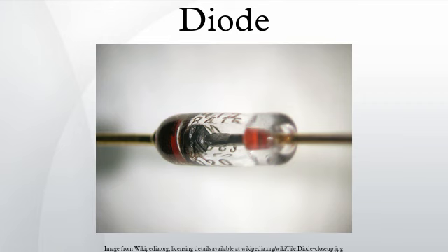These are Avalanche diodes designed specifically to protect other semiconductor devices from high-voltage transients. Their PN junctions have a much larger cross-sectional area than those of a normal diode, allowing them to conduct large currents to ground without sustaining damage. Varactor diodes. These are used as voltage-controlled capacitors. These are important in PLL and FLL circuits, allowing tuning circuits, such as those in television receivers, to lock quickly.